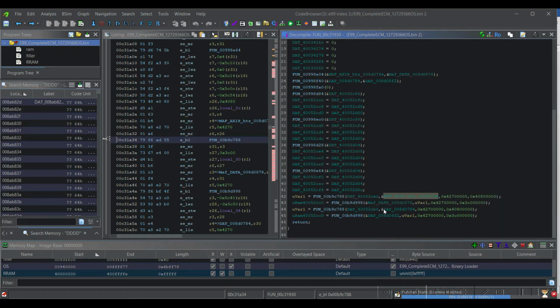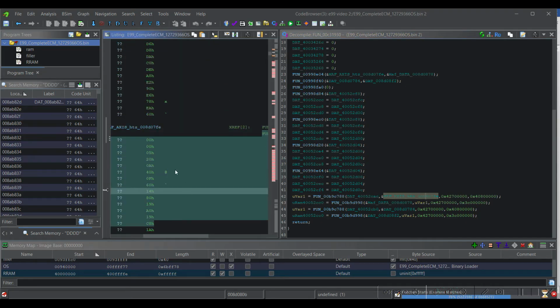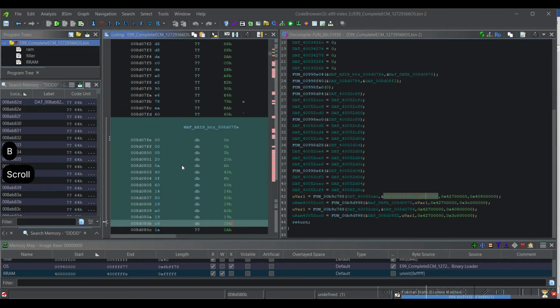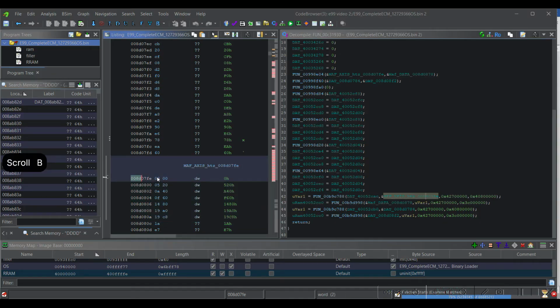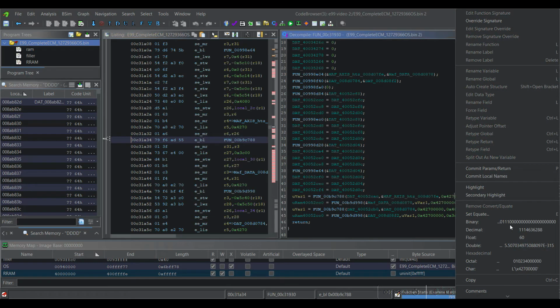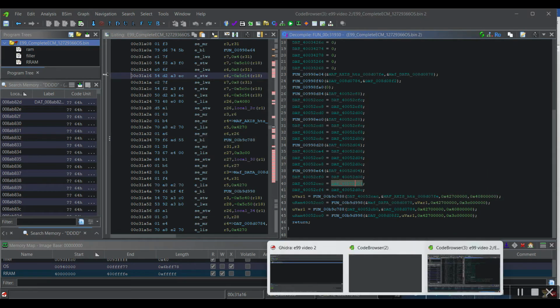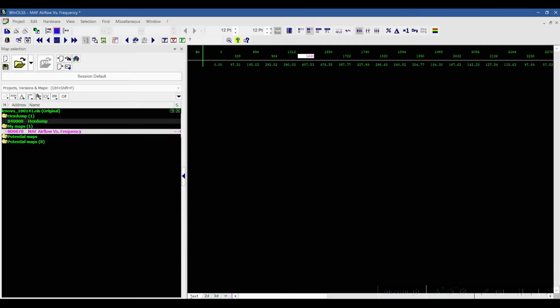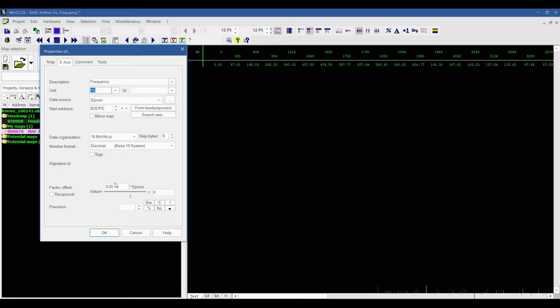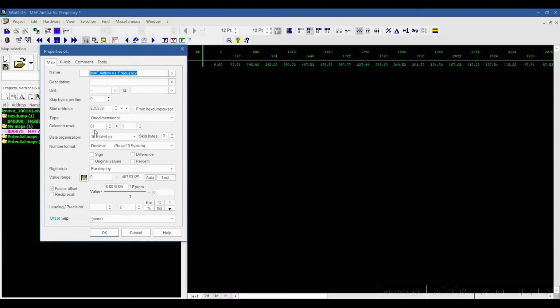And we can reverse engineer this, but what it's doing is 16-bit high-low. So this is considered 0, and then 1, and then 2, and 3, and 4, and so on. So this value 60 here is telling us that it's actually 61 long. So if you go into properties, the mass airflow sensor function or scalar, whatever you want to call it, calibration map, is going to be 61 long, which is good.